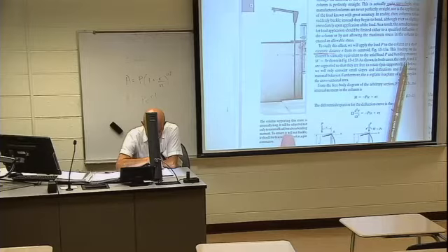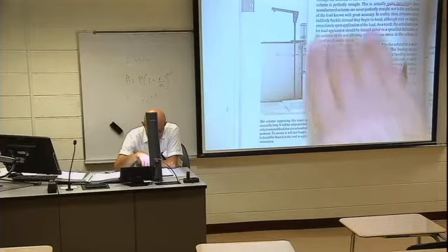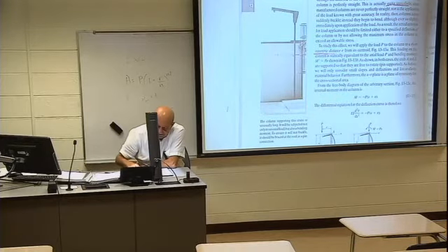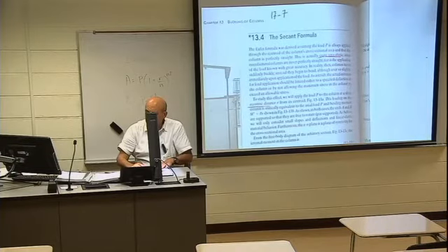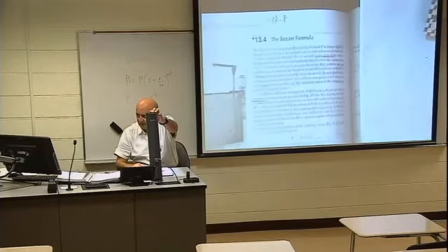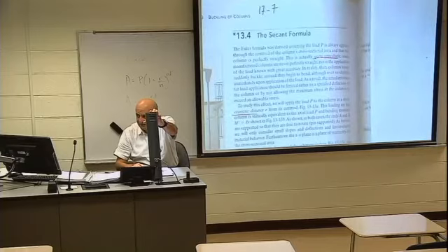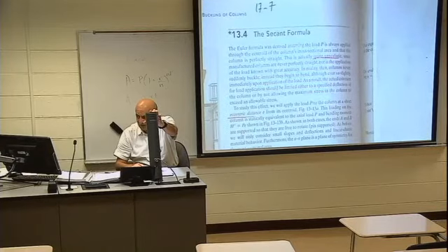It will be subjected not only to uniaxial load, but also to the bending moment because of eccentricity. To ensure it will not buckle, it should be braced at the roof as a pin connection. Okay, but the main thing is that we are dealing now with a non-ideal situation. That is the secant formula.